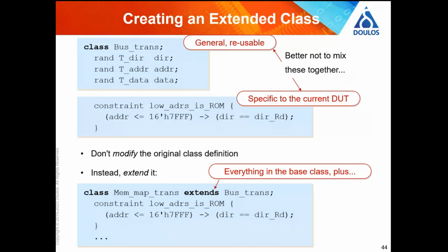So you can write your test bench in SystemVerilog to work with a fairly basic transaction, and it will also work with this specialist transaction as well, either because you want to do a different test or because you created the test bench last year for a different project and you want to reuse it. So it improves reuse as well.